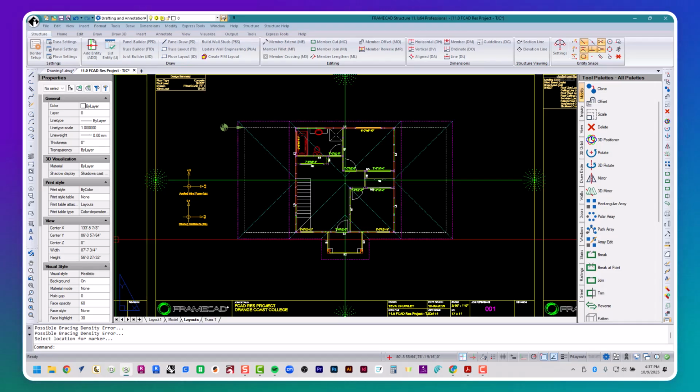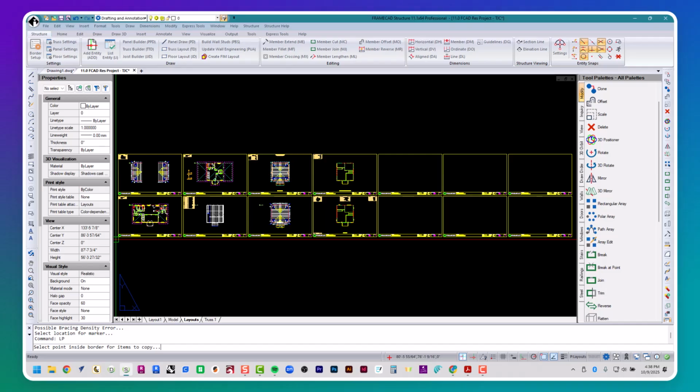Before we build our wall panels, we can display our load paths from our upper roof trusses down to our walls. This can be done by initiating the LP load path command. This is purely a visual representation of the load paths and is not a required step of the load transfer process. Loads are only transferred once the reference markers have been placed and the wall engineering has been activated using either the PCB, PPD, or PUA commands.